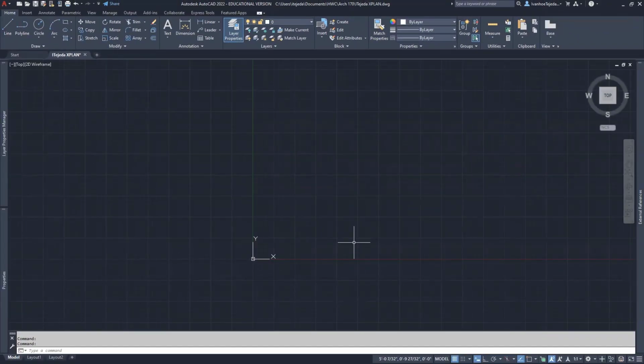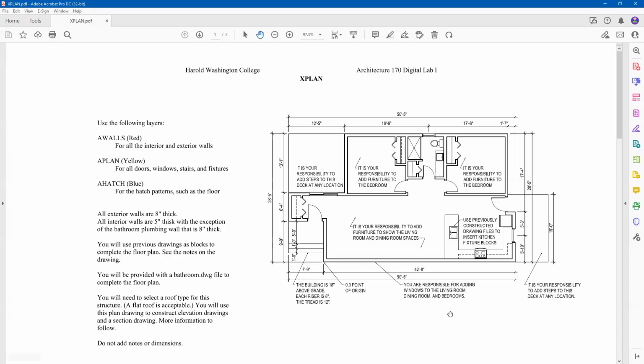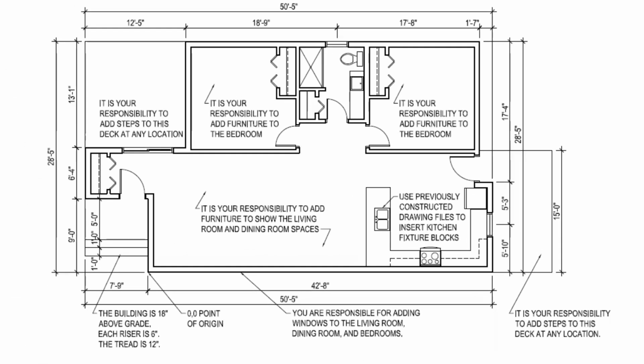For a drawing like this, where to begin? Because it can appear to be overwhelming, especially if this is the very first time that you're doing a drawing like that. Make this 0,0 right here. It's one of the closest points towards the bottom, towards the left, and that's usually where we anchor our drawings. And then from there, what I'm going to recommend is that you place all of the exterior walls, that you at least establish that footprint here.